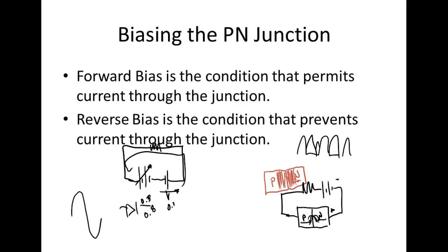When you get into DC machinery, he wanted to call an AC generator an alternator, and that's not true. The only time we really use the term alternator is if you're in cars. The first generators they put on cars were DC generators. And then when the diode came along, they figured out they could take AC and convert it into DC. And AC generators are a lot cheaper than DC generators for the same power.